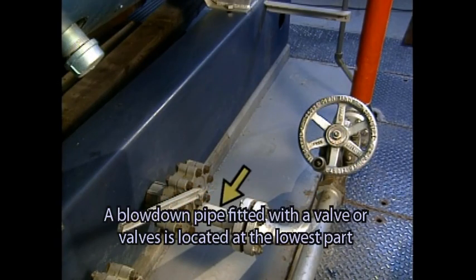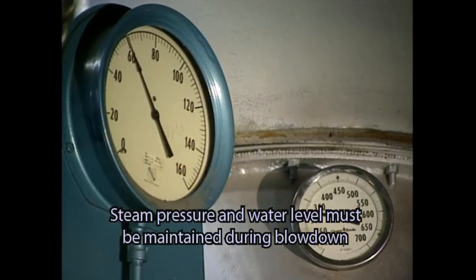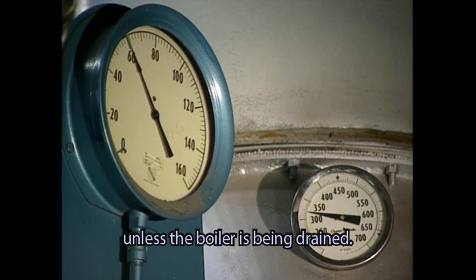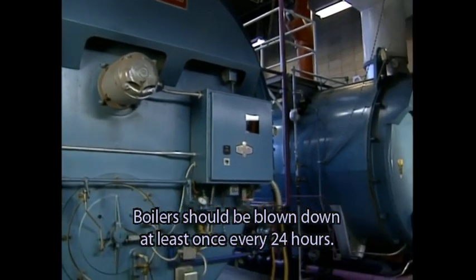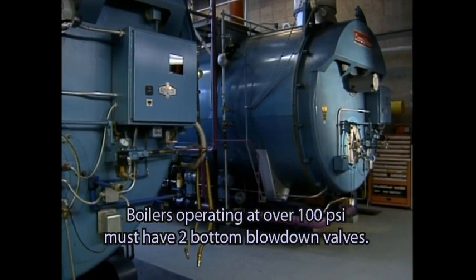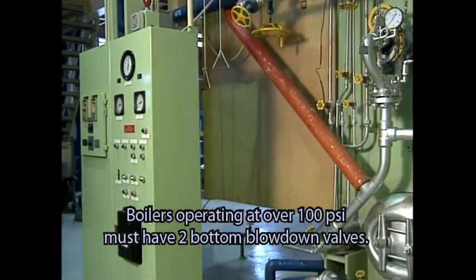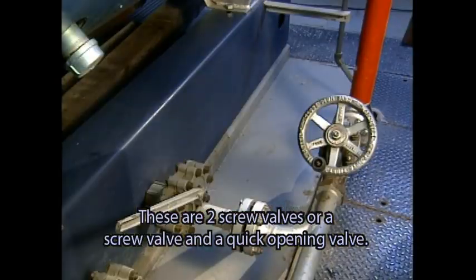A blowdown pipe fitted with a valve or valves is located at the lowest part of the water side of a fire tube boiler or the mud drum of a water tube boiler. Steam pressure and water level must be maintained during blowdown unless the boiler is being drained. Boilers should be blown down at least once every 24 hours. Boilers operating at over 100 psi must have two bottom blowdown valves. These are two screw valves or a screw valve and a quick opening valve.